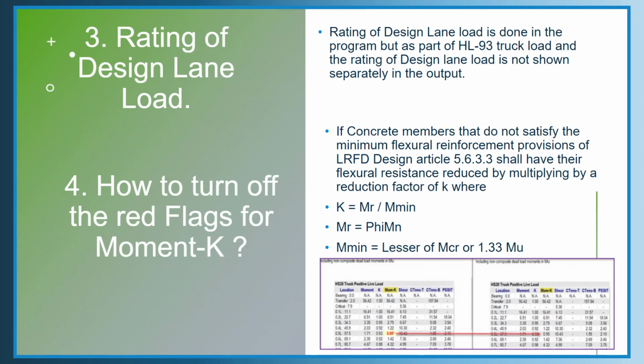The rating of design lane load, this is quite a common query from the users. The rating for design lane load is done internally in the program, but as part of the HL93 truck load, and the rating of the design lane load is not shown separately in the output as it is part of the HL93 truck rating itself.